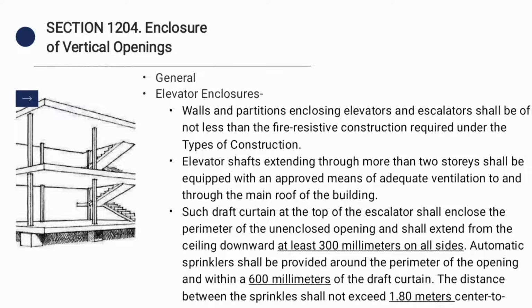And now let's proceed to Section 1204 about the enclosure of vertical openings. So for the general requirements, vertical openings shall be enclosed depending upon the fire resistive requirements of a particular type of construction as set forth in the code. So for the elevator enclosures, the walls and the partitions enclosing elevators and escalators shall be of not less than the fire resistive construction required under the types of construction.